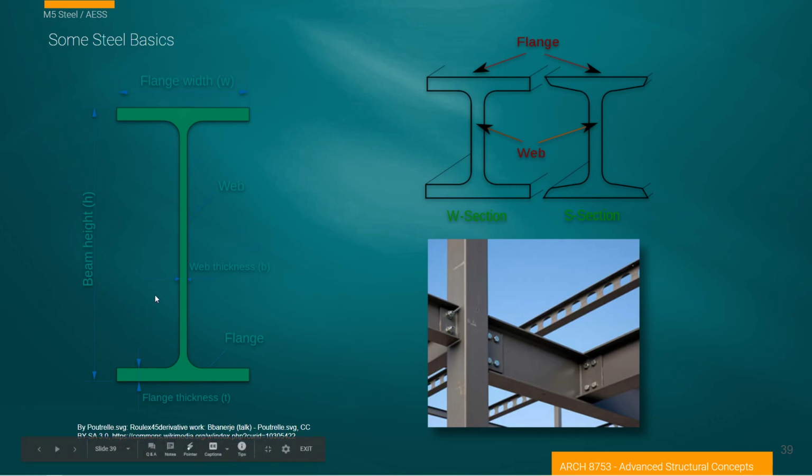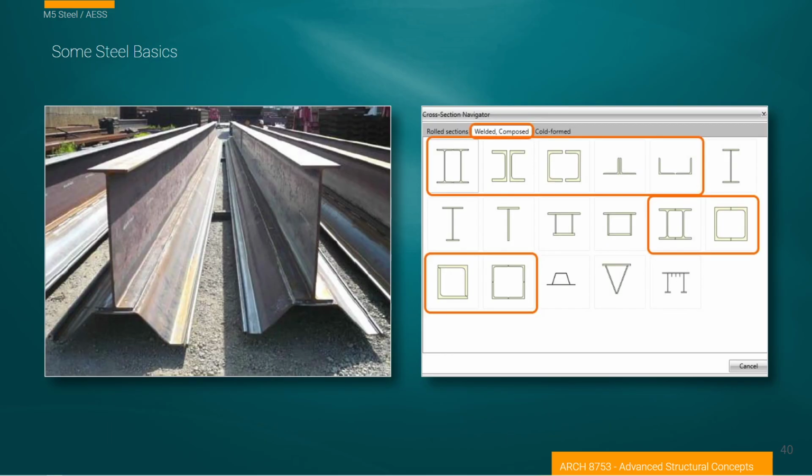And I've got the nomenclature here. One of the things to take note of is that the two typical defining terms of the beam are its height, how deep it is. So it would be a W, let's say a 12 by X. X might be 15 or 20 or 75, and that second designation, that 12 by whatever, is the pounds per foot. And maybe I'll try to clarify that in some other slides here.